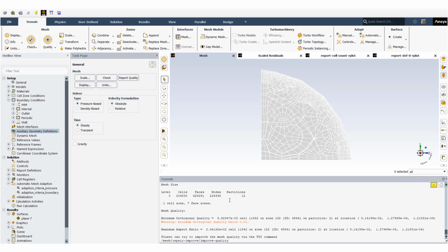This is very important to note, because otherwise mesh adaptation can really worsen the mesh quality, as we are seeing here, and also does not necessarily give a better calculation, for example the pressure drop changed less than 2% compared to the initial value that I received from the original mesh. So what is the solution? Either we need to have a good mesh to start, not only regarding the minimum orthogonality, but also to be sure that we have good resolution to capture the geometrical features, for example where I have the curvature, and also a good representation of the flow features, for example pressure drop.